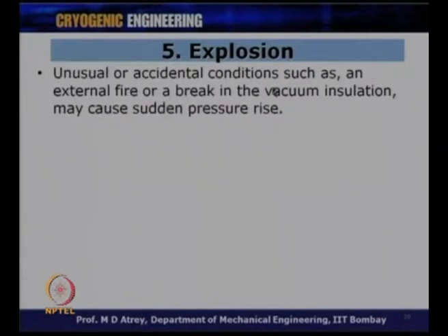Unusual or accidental conditions such as an external fire or a break in vacuum insulation may cause sudden pressure rise. Because of such aspects, you can get a lot of heat inleaks to the cryogens, which can result in sudden pressure rise. This may lead to an explosion.